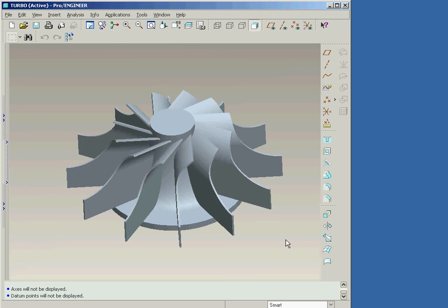In this session, we'll illustrate how to create a radial pattern that is based on a sketched feature. During the creation of the pattern leader feature, we'll use the makeDatum operation in order to create an angular dimension that will then be incremented to produce the pattern.